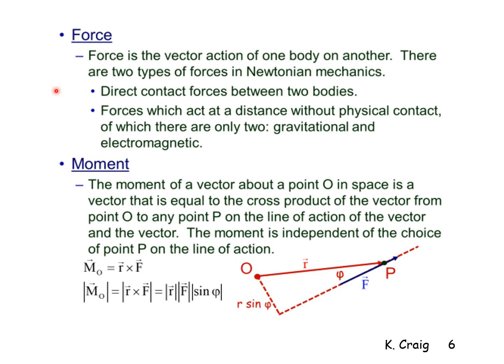We do not consider the nuclear forces, atomic forces. We're dealing with macroscopic, large-scale dynamics problems. The only other forces that exist then are contact forces. No contact, no force. So see where the rigid body contacts its environment, and there will be forces at that point of contact. No contact, no force. Centrifugal force, Coriolis force, these are fictitious forces. They're not real. You will understand this as we proceed.